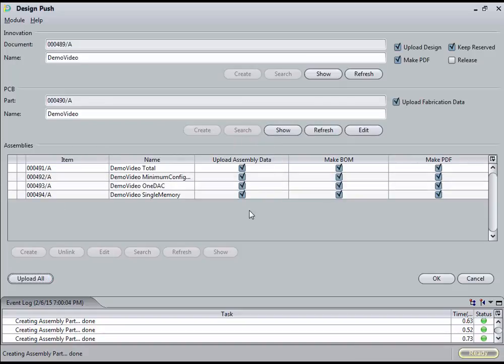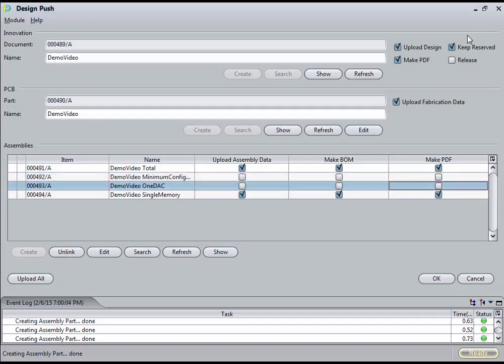It would create all elements and set all checkboxes in addition. Only the checkboxes Release and Keep Reserve are not touched by this button. Those can be selected or deselected based on the actual process flow milestone. It is possible to continue with the design process, hand over the design to somebody else, or handle release aspects. Based on company needs, the release checkbox could, for example, just release the design container, release all created elements, or start a release process within the PLM system.